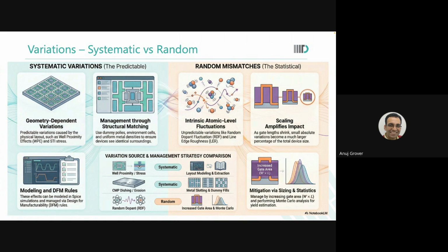But in reality now, what happens when you do the STI implant? Just after the device, within a few nanometers, a few tens of nanometers of the gate region, where your channel is going to form, within a few nanometers of the gate region, you have broken the crystal and you have put something else there.